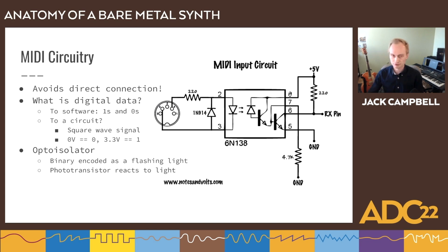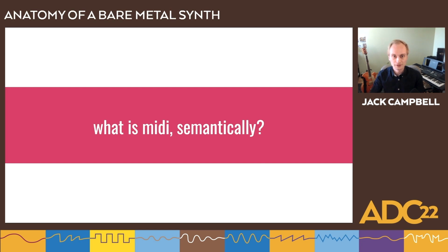So we've successfully generated an analogous data signal on the other end, on that RX pin that we plug into the DAISY. We get the correct data, but it has been converted from electricity to light and then back to electricity. And it's pretty neat. This is part of the MIDI spec too. So any MIDI compliant device will have this on its MIDI input.